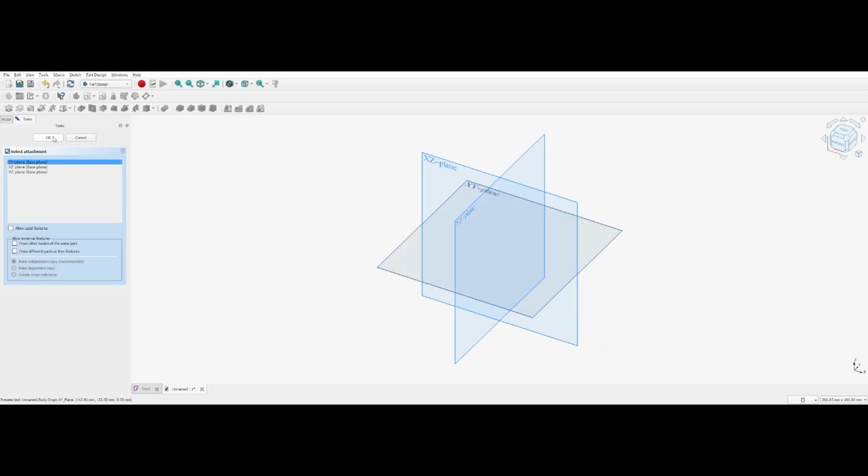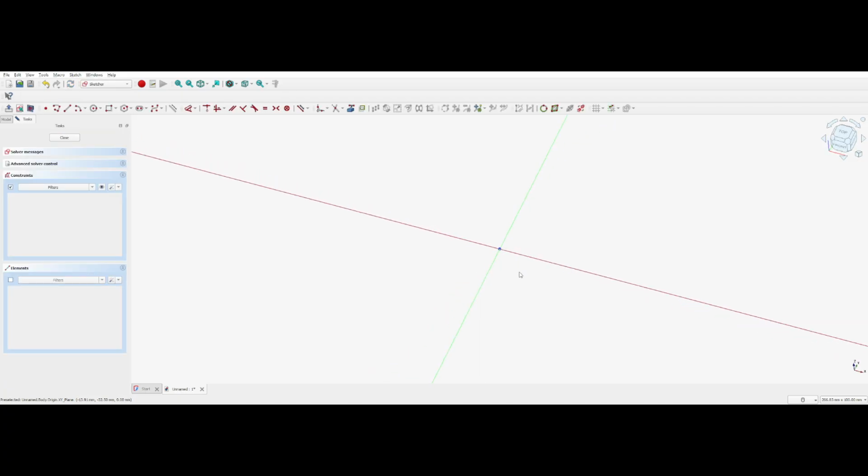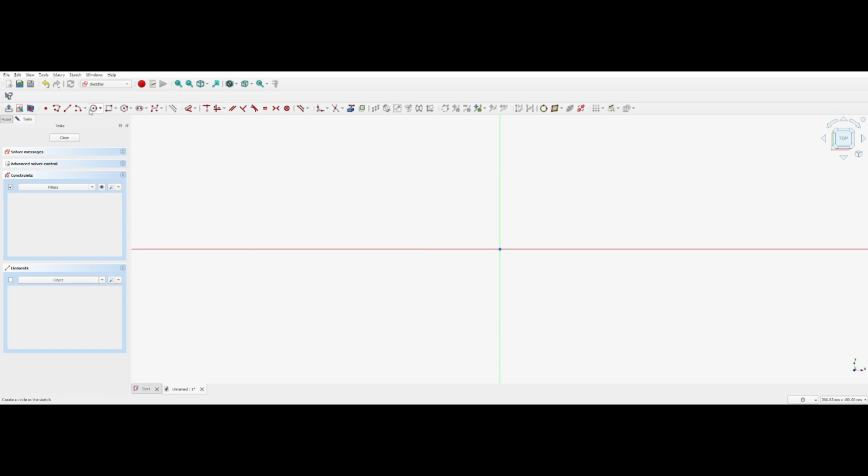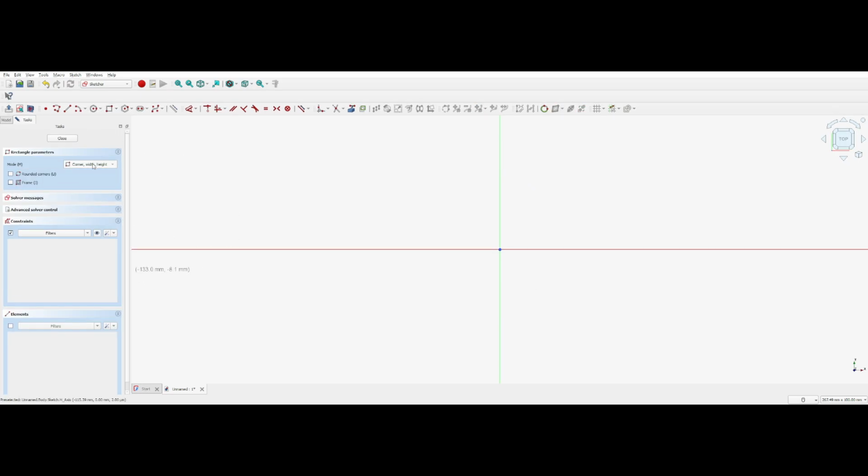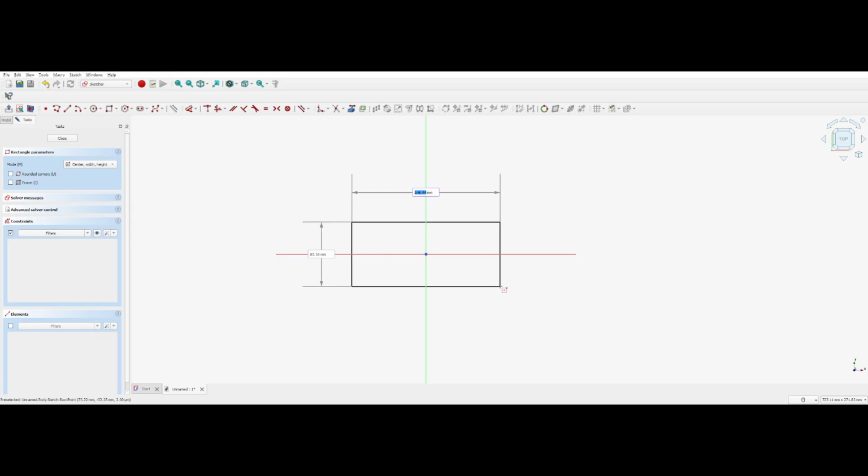You can start on a plane, X, Y space. That's your basic horizontal. Because it's a tournament tray, we are going to make a square. You can pick any option for making a square. I like centered because it makes everything from the center of geometry. If you click on a node point, any dot, it'll home to that location, so this will be at 0, 0.